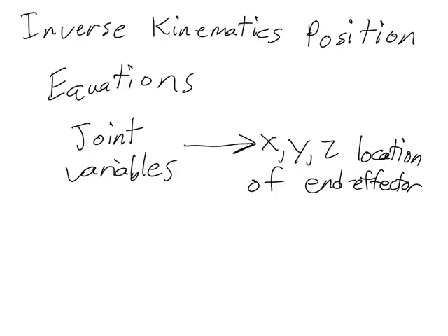For example, once you have the inverse kinematics equations that apply to a Cartesian manipulator, you can use those equations anytime you have to do a calculation for a Cartesian manipulator. You don't have to rederive them for every new manipulator you might encounter. In this video, I'm going to show you how to derive the inverse kinematics equations for one or two manipulators, and then I'm going to give you the equations for the rest of the manipulators.